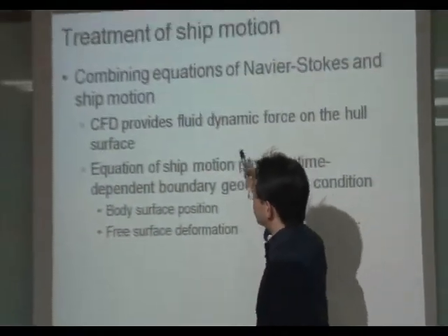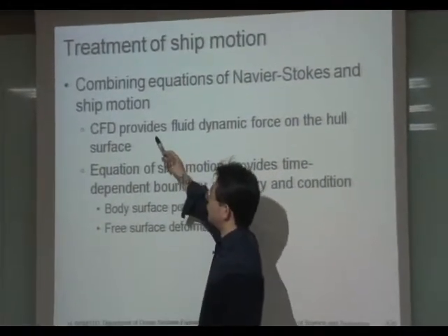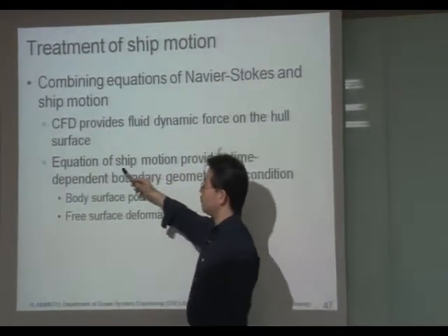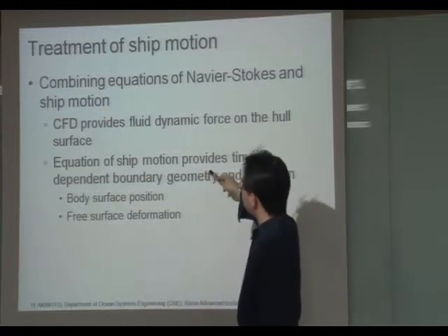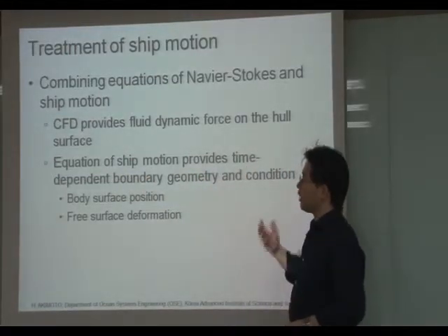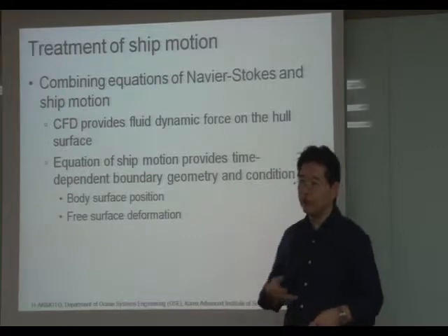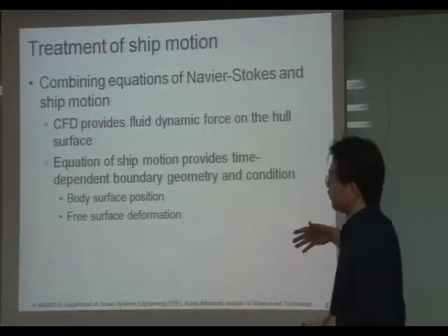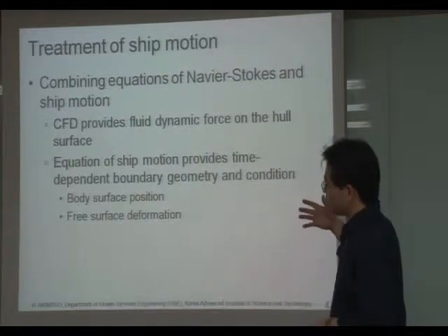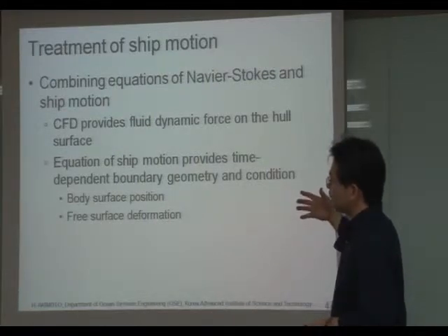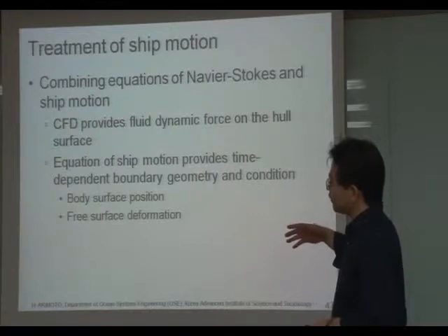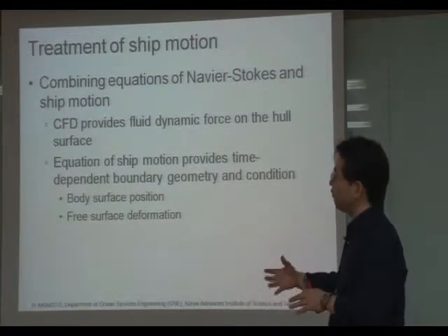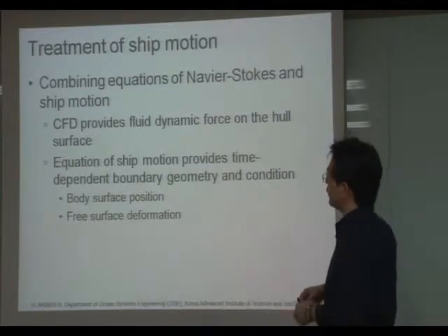And this is the interaction from CFD to the equation of motion. And also, the equation of ship motion provides the time-dependent change of boundary configuration, because the surface of the ship is also a boundary of the fluid simulation.